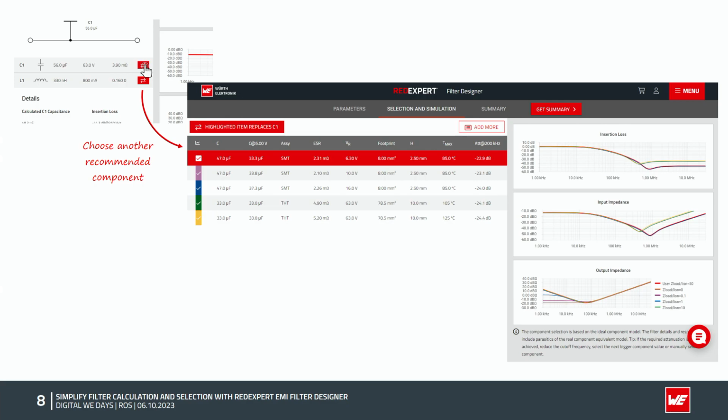In this case you can select some capacitors by different colors, and get the characteristics of these components in the same color on the right side to compare them together. For example, an MLCC with a polymer capacitor to see the effects. You also get a column where you can see, especially for MLCC, the DC bias influence and how much capacitance is reached at your working point.